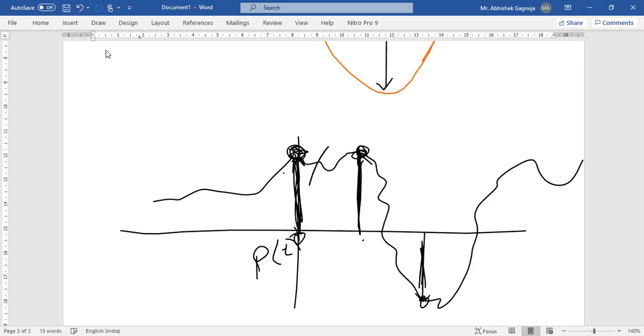So the rest everything is discarded, since we are going to sample the data anyways for decision. And hence, if we use a pulse that follows the criteria mentioned by Nyquist, the entire intersymbol interference possibility is removed. It is diminished, it is over.